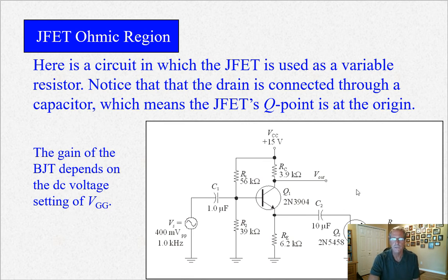Right here, yeah. Okay, so this is a voltage-controlled amplifier. This is a BJT. This is our standard common emitter amplifier, which we looked at a couple weeks ago. VL is taken at the collector. But the gain of this circuit is adjusted. You can adjust RE to adjust the gain of this. And what we do is we put this FET in parallel with it to change its resistance. So this Q2 actually will change resistance between its drain and source, which is in parallel with RE. It'll change its resistance in response to the gate voltage. So you have a voltage controlling a gain. So it's a VCA, voltage-controlled amplifier.